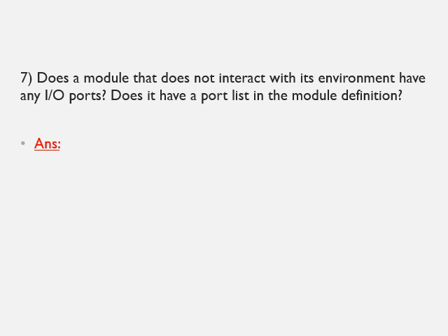The answer is yes. It can have I/O ports even though it is not going to interact with its environment. Then does it have a port list in the module definition? The answer is no. If it is not going to interact with the external environment, then it need not be mentioned in the module definition line.